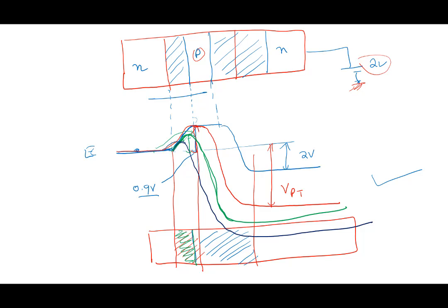So if I were to draw what would happen, let's say collector IC versus VC, and VBE is 0, right? Almost negligible current. But the moment you start reaching punch through, it begins to increase. The transistor is supposed to be off, but it's starting to conduct, which means the switch is no longer in the non-conducting state.